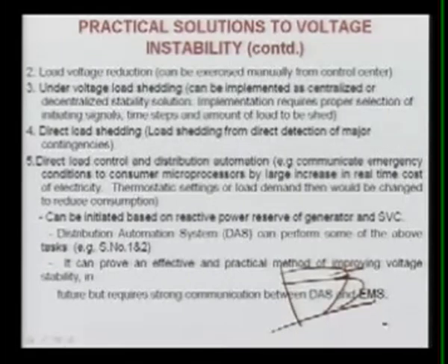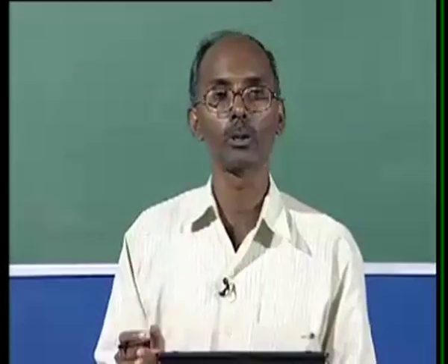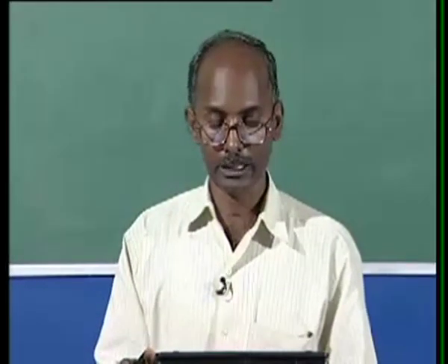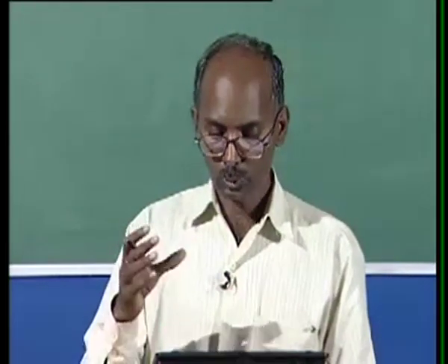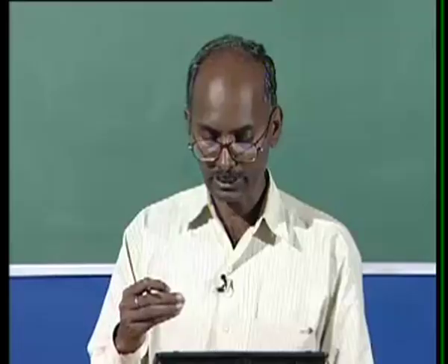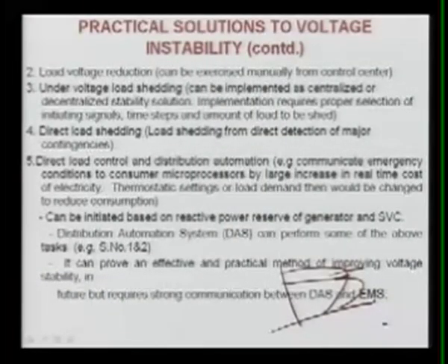Now this load voltage reduction means that if your voltage is reduced at the load buses, you can reduce the load of the system, and that can be exercised manually from the control centers. So what you can do is reduce the loading of the system, then you can increase the voltage, and then your system will be more healthy with respect to voltage instability.